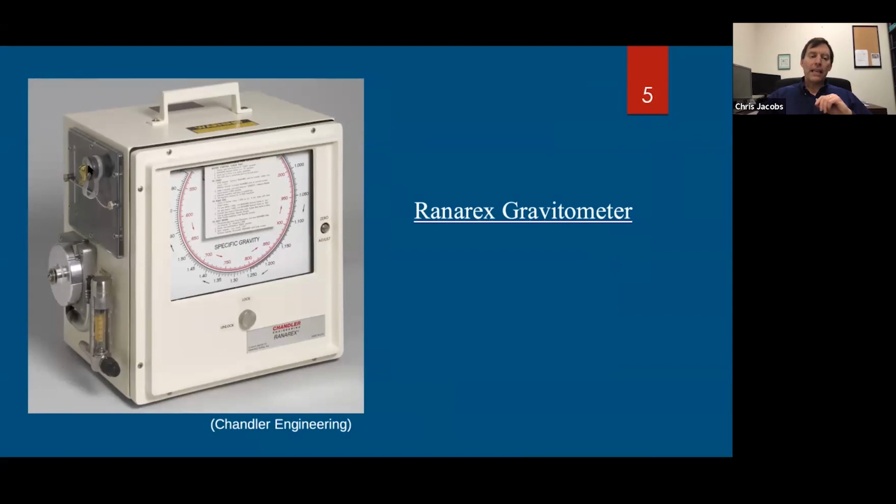You can pour the desiccant out into some kind of a pan, put it on an open top burner, not a Bunsen burner so much, but like a hot plate or a stove, and you heat it back up. It may take 15 minutes. Once all the desiccant is blue, you can use a funnel. You can pour it back in through this hole, put this connection back on again, and you are ready to use the machine.